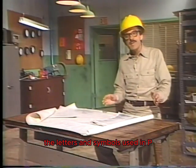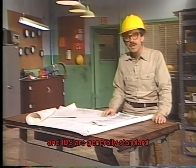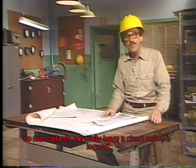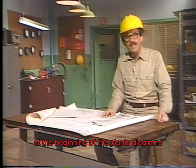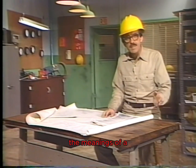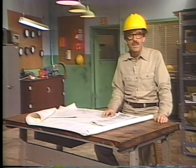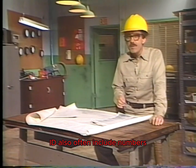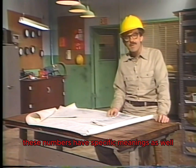Now, although the letters and symbols used in P&IDs are generally standard, there can be some variations from plant to plant. So most plants normally have a chart called a legend at the beginning of the plant's diagrams. The meanings of the letters would typically be identified in the legend. The instrument symbols in a P&ID also often include numbers. These numbers have specific meanings as well.